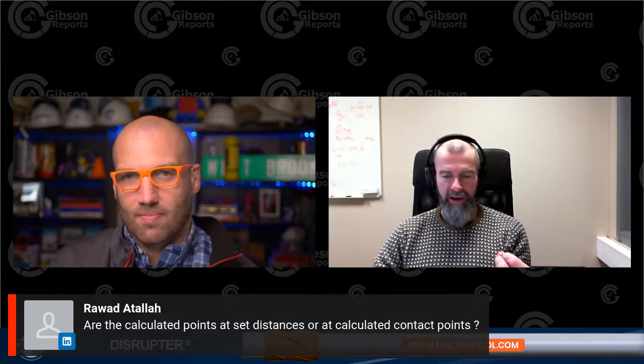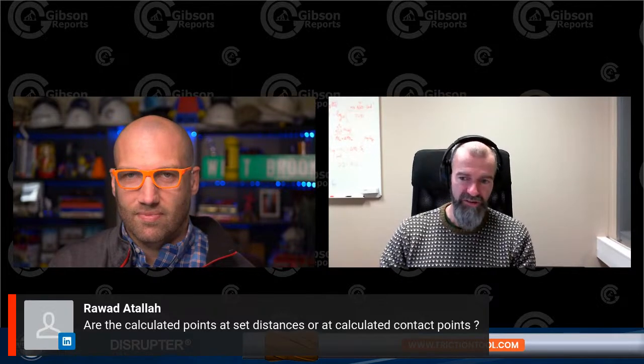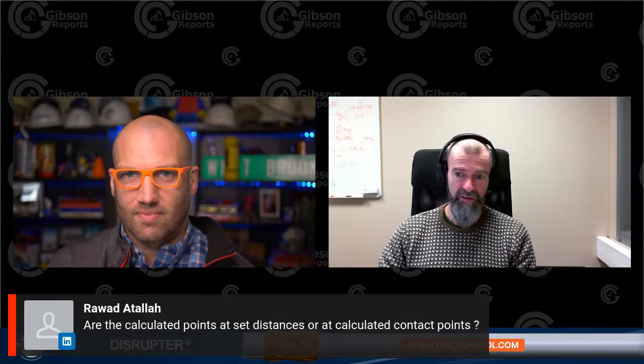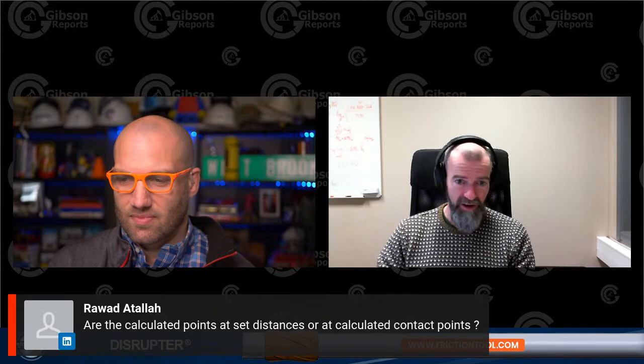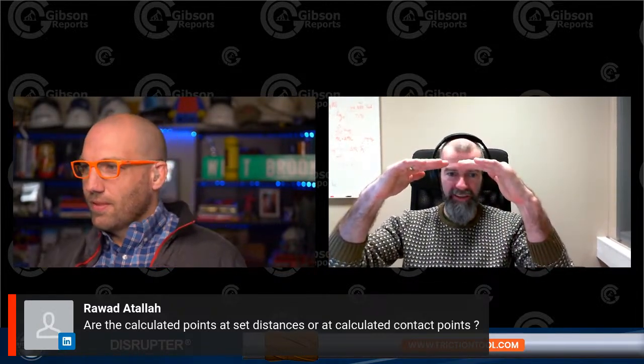So in the middle of a drill pipe, it will be hanging in the air all of the time, or in the mud all of the time. It won't be touching anything unless it's subjected to an extreme dog leg with a high degree of tension. I didn't mention it in the presentation, but it was mentioned a week back, this bending stress magnification factor.